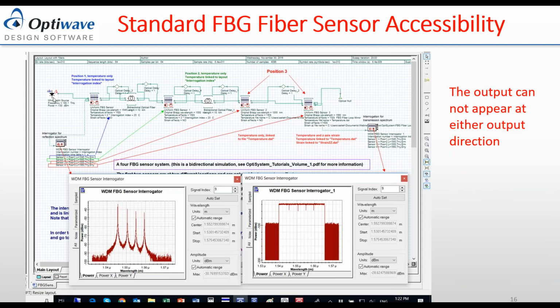If I put an LED here, a basic LED or broadband source, and there is a drift in the center wavelength, especially with a narrow band grating, then you should be able to reflect. With a light emitting diode broadband, you reflect the band which is the Bragg grating wavelength, and the other wavelengths are going to pass through.